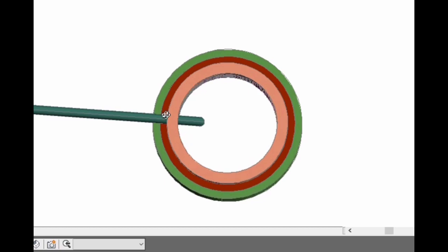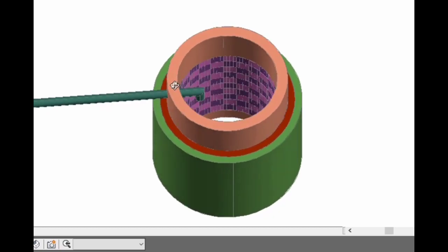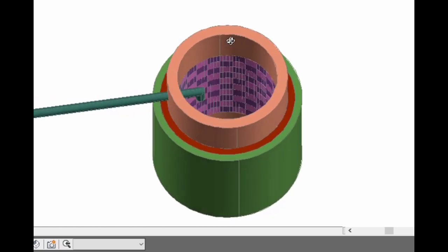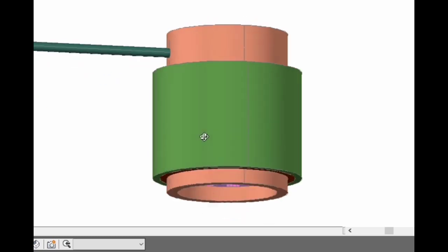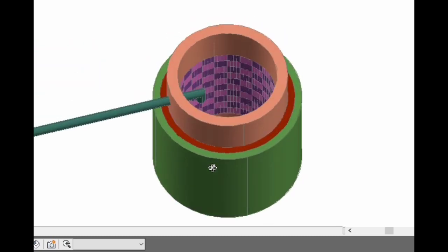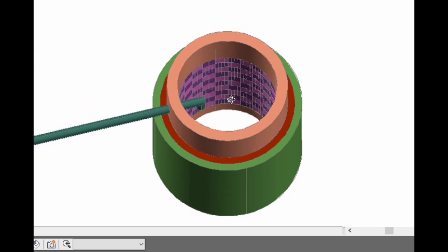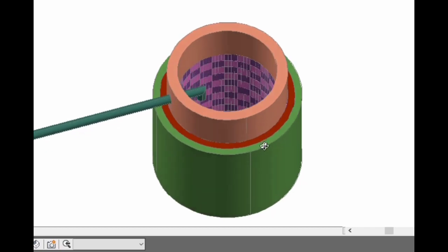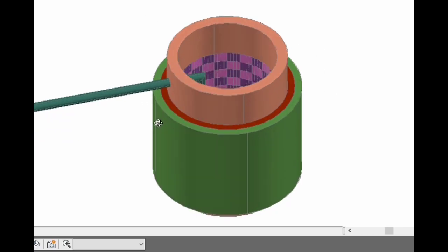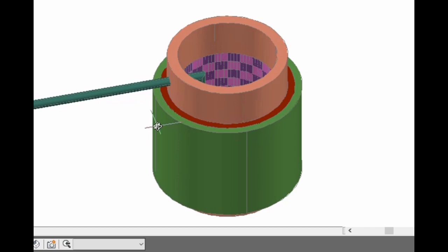This is the top view, the second class brickwork at the top and at the bottom, in between with the dry brickwork. Around this you will be having the brick aggregates of 50 mm size and coarse sand all around that. This is how the structure goes.